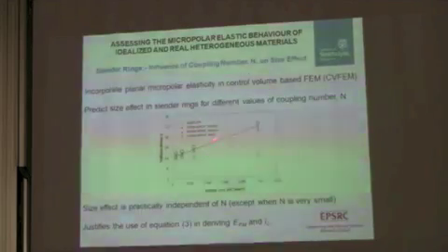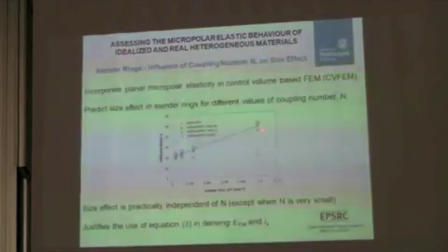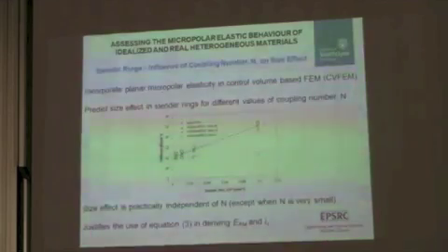In this set of data, shown by the triangles, I've reduced the coupling number down to a very small value, 0.15, but I still get a very significant size effect, which is very difficult to discern from the couple stress case. So the argument we make is that we're not really going to be able to identify the coupling number from doing tests on slender samples.